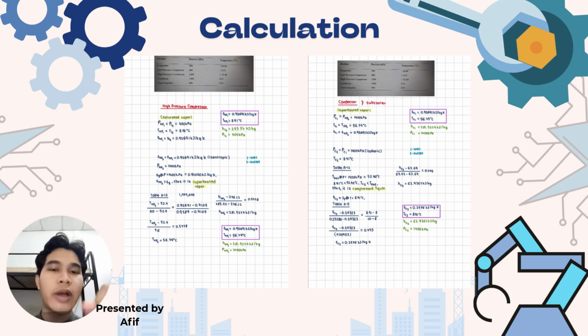And then when it passes to the condenser or the subcooler, in this case we are treating the subcooler and condenser as one component in one shell, because it is definitely not possible for the condenser to cool the refrigerant to a point where the expansion valve needs to raise the temperature back again. So we treat them as the same component. So the inlet of the condenser and slash subcooler is going to be the superheated vapor, and after it loses the heat to the environment or the surroundings, it will become compressed liquid. And the values are as follows for the enthalpy, entropy, pressure, and temperature.